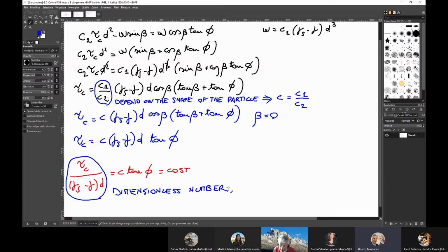I make this conclusion again. This dimensionless number, which is constant, if I were able to estimate it, then I would have solved my problem, because depending on the shear stress originated by waves, which I can plug in this equation instead of tau c, I can estimate the size of the units that I need for critical conditions. And then if I want a more stable condition, I can increase the size of the unit. Basically, this demonstration gives me a way to check the stability of the rock and armor units.